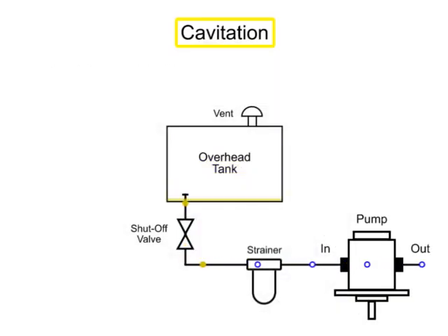Cavitation is often characterized by loud noises, such as grinding or as if there are marbles in the pump, and pitting damage to parts as material is removed by the bubbles. If fluid systems are properly designed and properly maintained to prevent dirt or air entering the system, operation will be efficient and reliable.